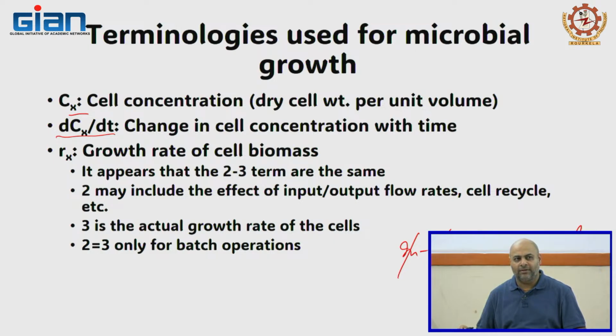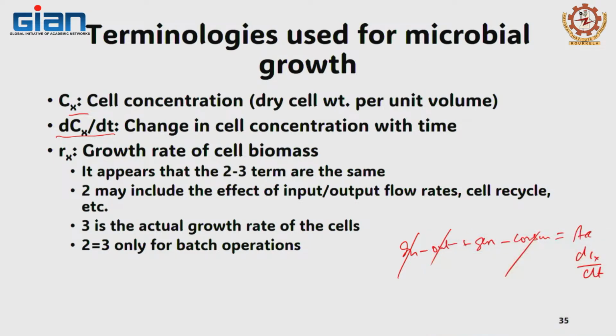Consumption of what? Am I balancing substrate or am I balancing the cell? Am I consuming the cell? So, the only thing that you will have is generation, right. So, let us say that I will give it as Rx, but it is a volumetric generation, volumetric accumulation, because the V remains constant. Got the idea? This is actually your design equation for your batch reactor.